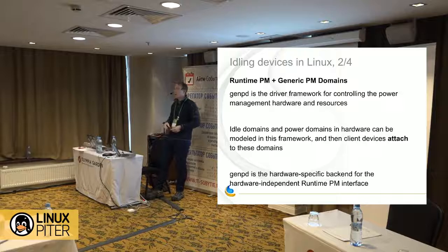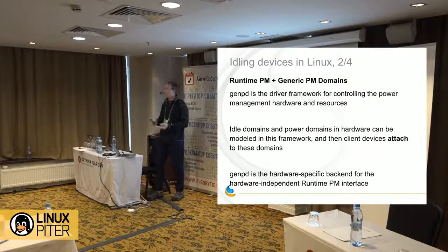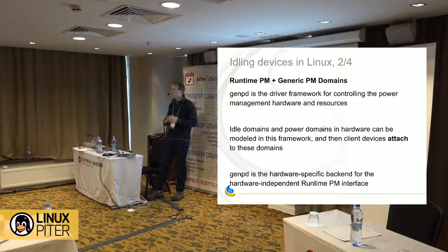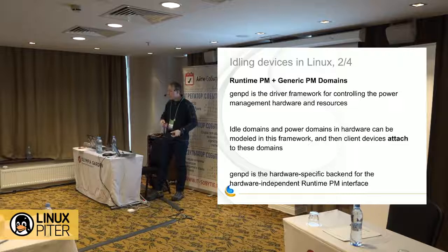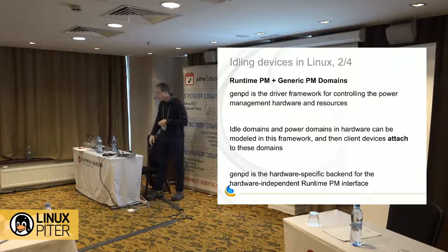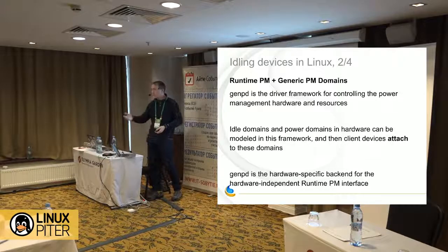Or for a more basic ARM platform, it might directly manage clocks and regulators within the driver. But this is the actual Linux device driver that talks to the PM hardware. And then all the different client drivers that use that PM hardware attach to this generic power domain. And again, this is just for idle. This is just for turning things on and off.